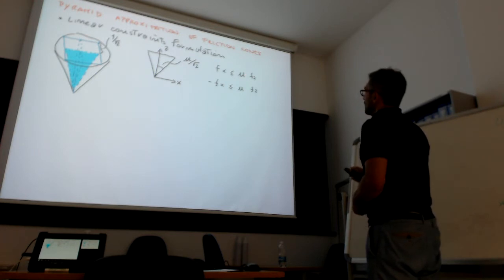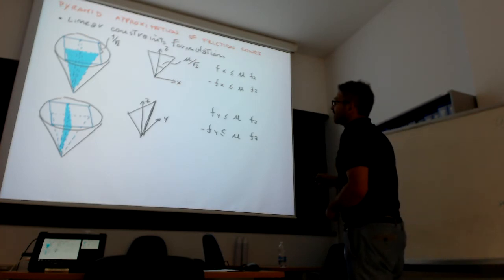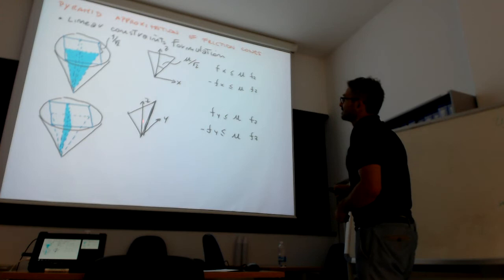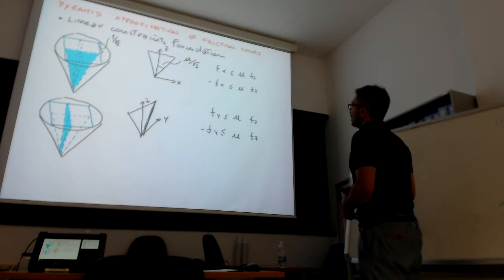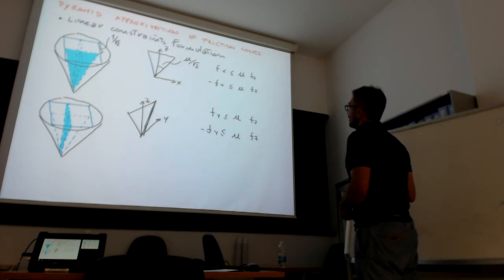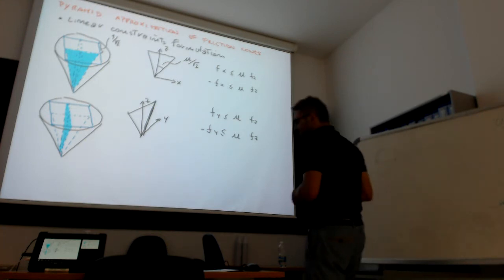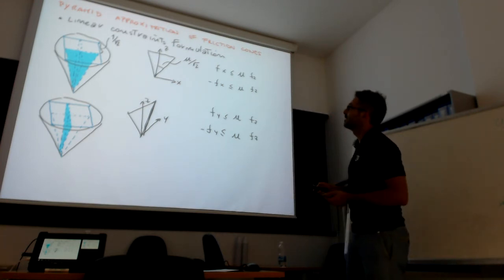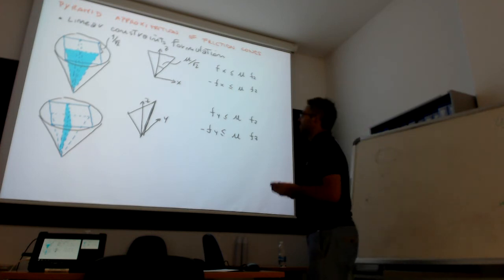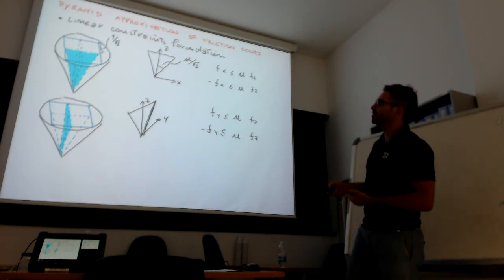And if it is in this quadrant, then this other inequality holds. While in the other slice, we have the same thing for the y component, positive and negative. So with all this, we are sure that we have the polytope pyramid approximation as a constraint, and that the force will be inside this polytope, that is this pyramid. And this pyramid is an inscribed approximation of a cone.